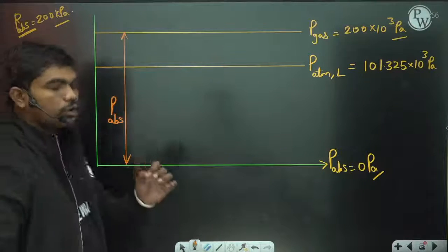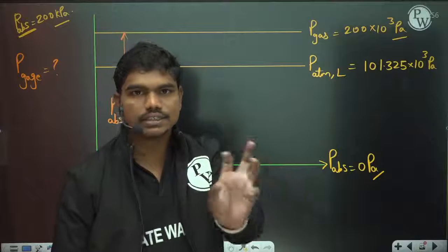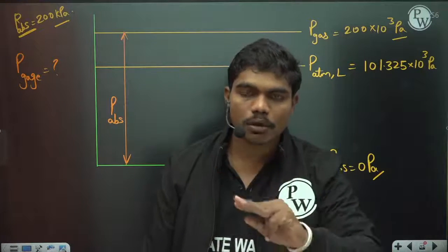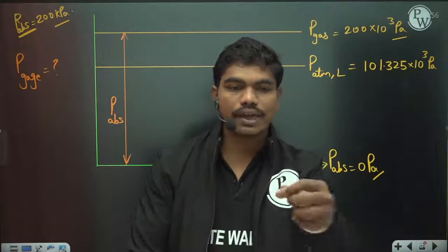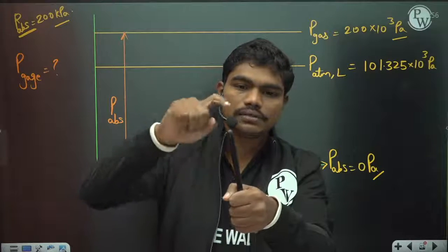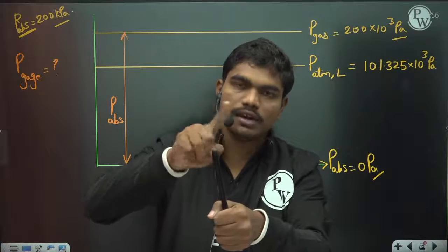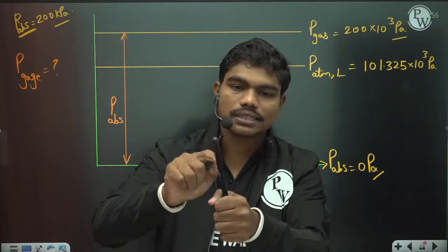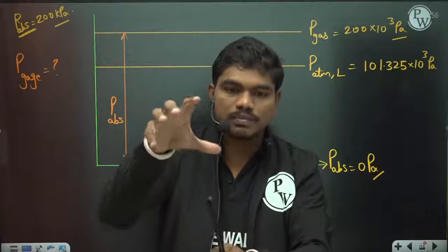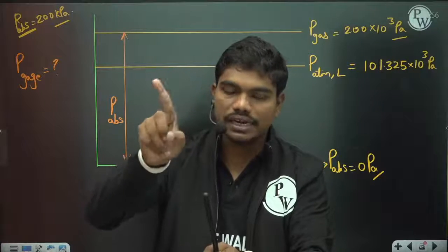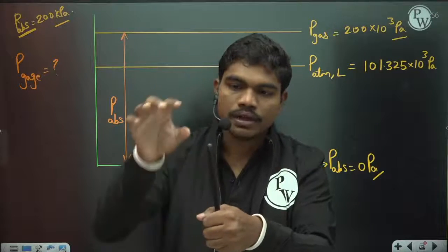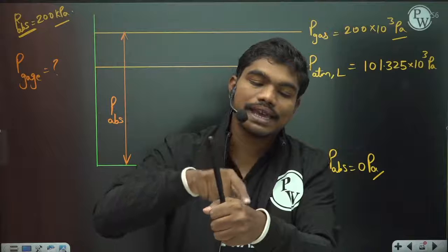when I'm talking about a gauge, normally if you take any pressure gauge, those pressure gauges will give you the gauge values of the pressure. They don't talk about the absolute values. Suppose I connect a pressure gauge to a gas tank. Digital meters nowadays have some software calculations and give absolute values, but the old pressure gauges have a dial with a needle. Whenever you put this pressure gauge into some medium, the reading is nothing but the gauge value of this gas.